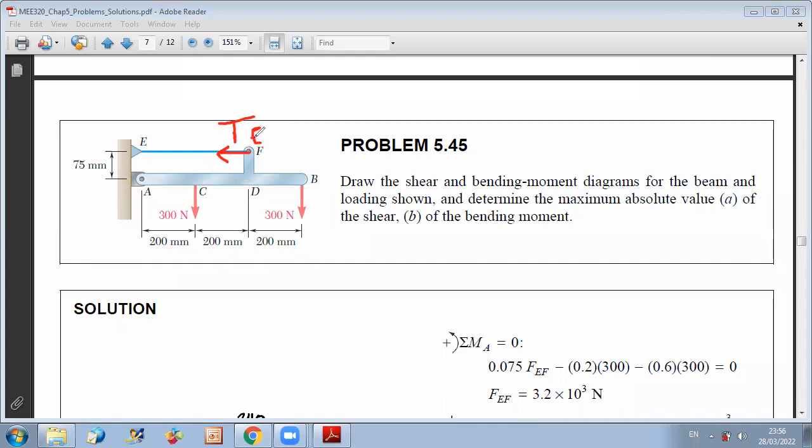Another method of thinking is to say I have the tension here at this level, TEF. So if at point D I put a positive force T and a negative force T opposing each other, TEF, TEF, then this is equivalent to a force and a couple at D, because these two forces are opposite in sense but have equal magnitude, so they can be replaced by a couple at D. So the couple at D, M at D, can be written as tension times this distance D.